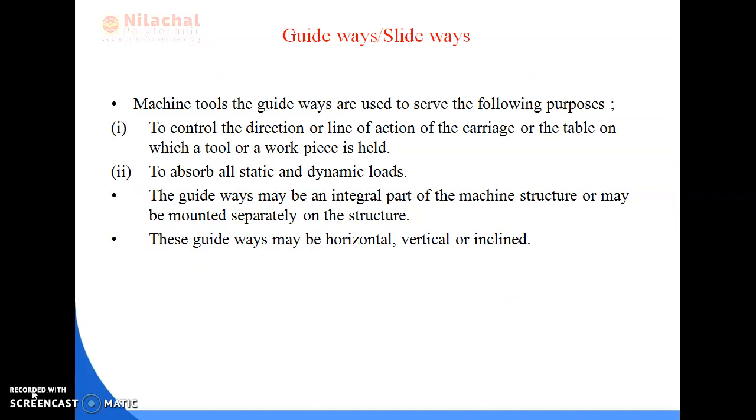Then guideways and slideways. In a machine tool, the guideways are used to serve the following purposes: to control the direction or line of action of the carriage or the table on which a tool or a workpiece is held. Means the guideways provide a path to the carriage or the table where the workpiece will be placed.